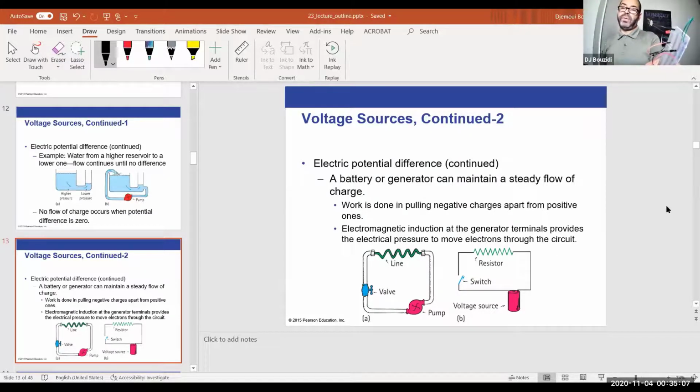So if you've ever played with a breadboard, this is the time for it, where you can make your circuits, where you can have fun, and do whatever you want to. So I'm picking it up from here and connecting it to this line. I don't know what this line number is. They're all numbered, by the way. And then it's connected to the resistor. From the resistor, the current is coming out, and it's coming through this negative side, which I'm connecting it to. This entire line has the same voltage where my second side of the battery is connected. So basically now I can connect it anywhere on this line and it's going to light.